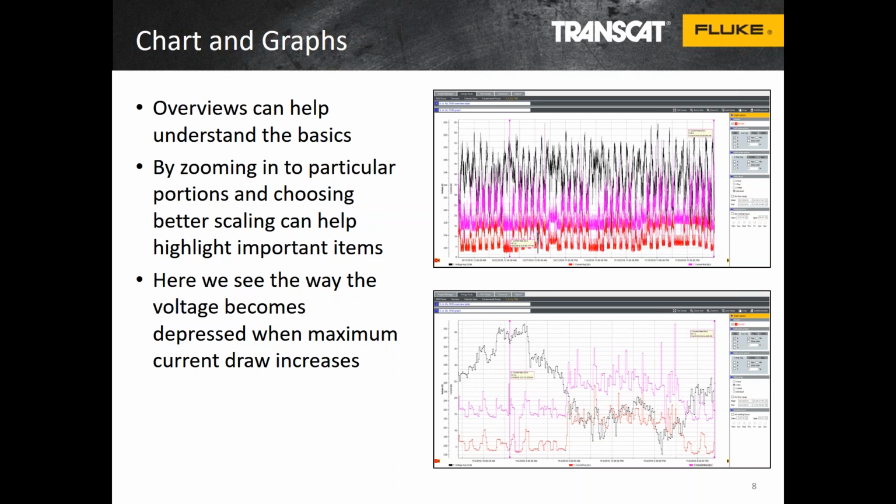as to what's happened. And on this bottom graph, what we can see is that we can see voltage, which is the black signal, and we can see the current. And we see a current trend where when the current's low along the bottom, that's kind of the pink trace, we see the voltage goes down. That's kind of normal because that's the activity in the facility. You'll usually see voltage drop caused by loads coming on and current going up. So there's a direct correlation between the voltage and the current. So just looking for those is important.